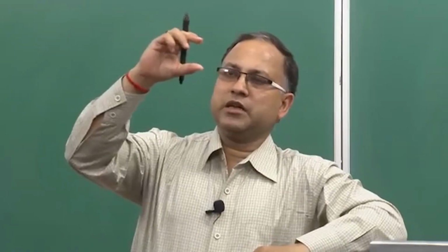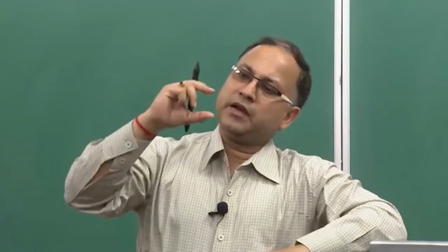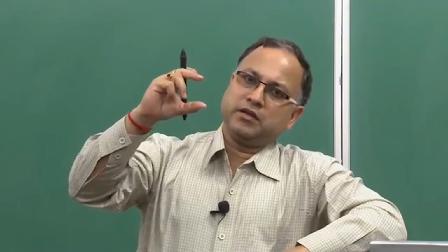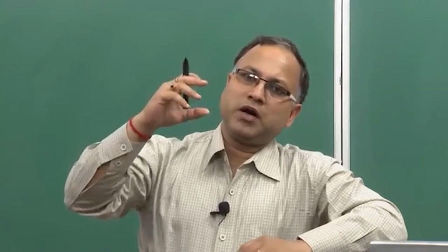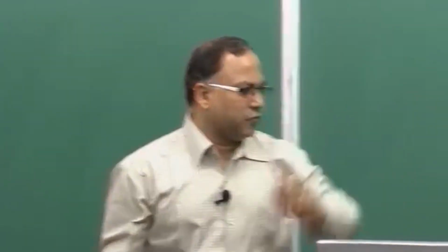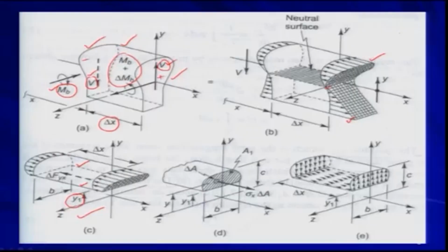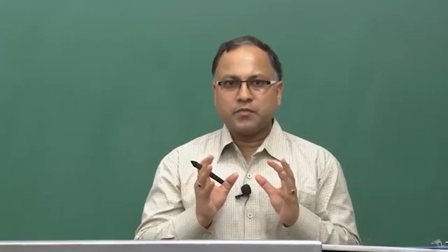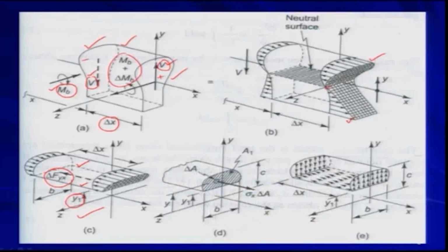If you consider a top part of the beam, and immediately after that there is one adjacent part, these two parts will be getting bonded at the interface. Therefore, you should expect one force which will be getting developed at this y plane along x direction, yes or no, to balance the forces acting on the x plane.